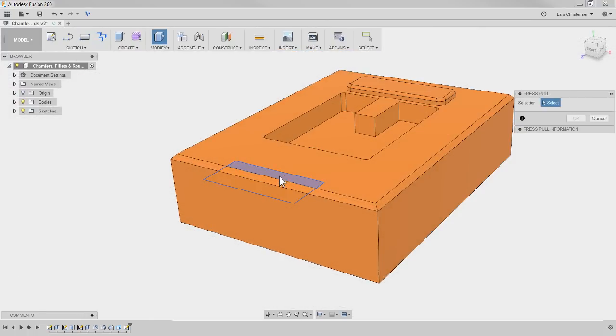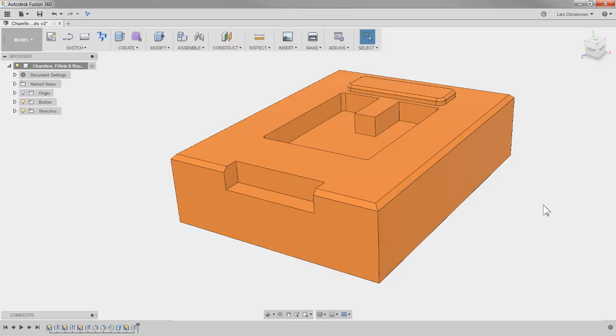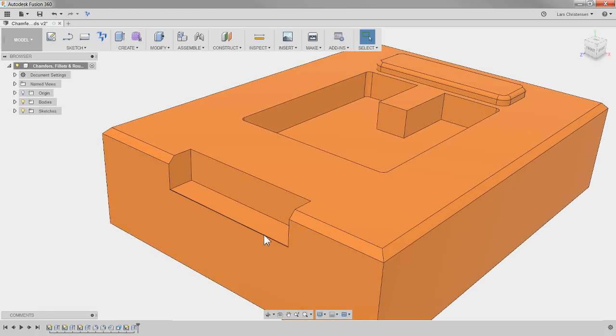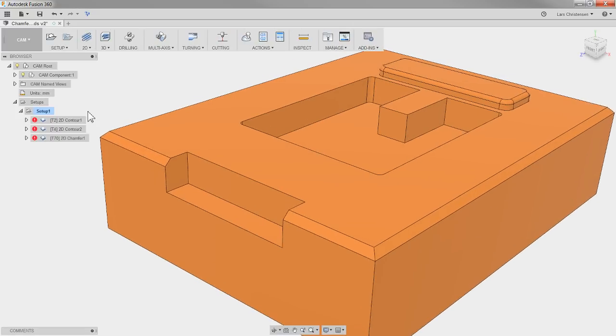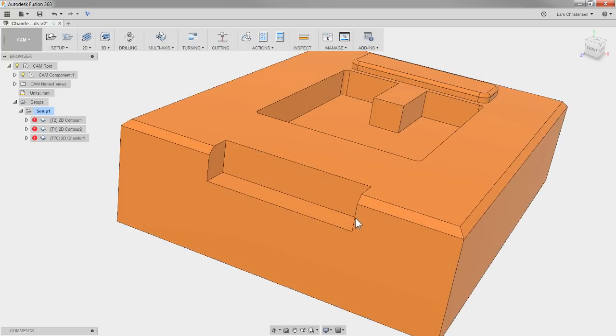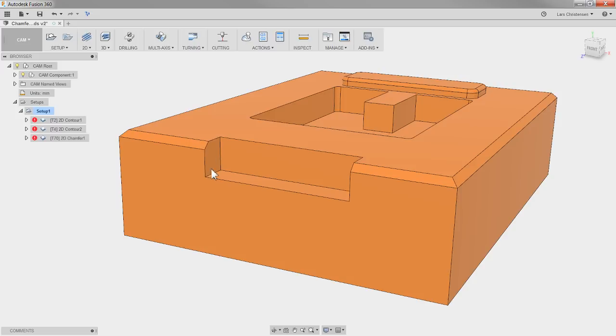Hit Q. Something like this, and you want to chamfer your part, and you're thinking, oh yeah, I want the chamfer to come in here and cut in here. Well, most standard chamfer tools would actually just chamfer the whole edge, which means you will hit that edge right there. Somebody who has ever tried this knows that awful sound when the cutter hits there.